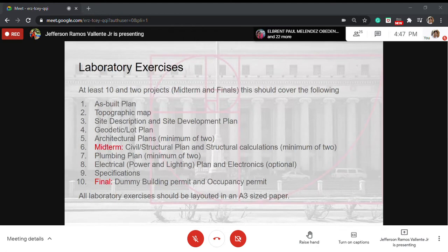Second is a topographic map. You need to use a topographic detail or do field surveys. Para makabalo mo kung ang structure will need to do filling, meaning magdugang baka o kita, or if you just utilize the terrain and add another floor. So this was the case in one of my projects where the client did not inform that the lot that they acquired from the developer is actually a 30-degree slope.